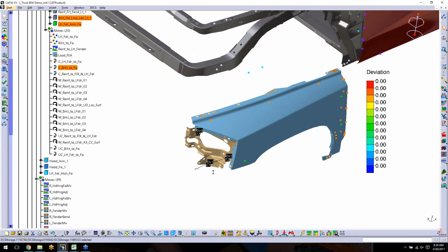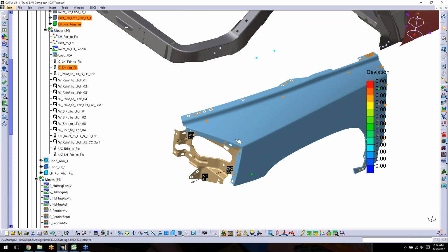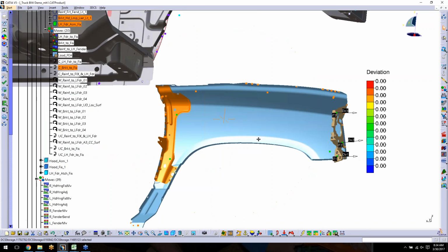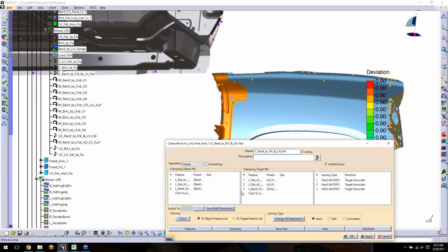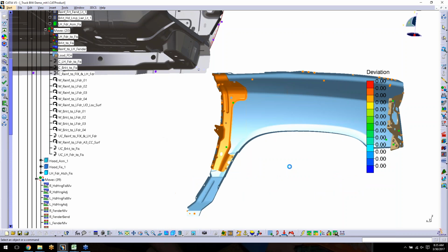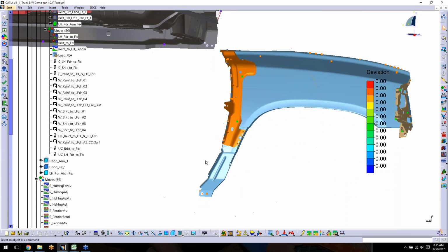Then we're holding the bracket at its datums in the fixture, and similar locating features are used for the reinforcement. Once they're all held in place, these are all hard clamps. There's 3 hard clamp points that will not introduce any more twist in the part because we need 4 points to introduce twist in the part, basically. So they're just holding a part on their datum.